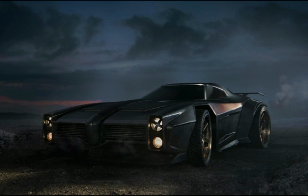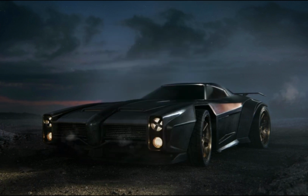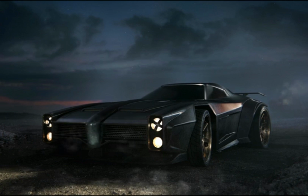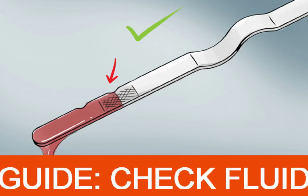General troubleshooting tips: scan for error codes. Use an OBD2 scanner to identify electronic faults. Inspect the fluid. Brown or burnt-smelling fluid indicates overheating or wear. Metal shavings in the fluid suggest internal damage. Listen for noises. Grinding or whining sounds may indicate a failing pump or gear damage. Perform a pressure test. Use a transmission pressure gauge to check for proper hydraulic function.